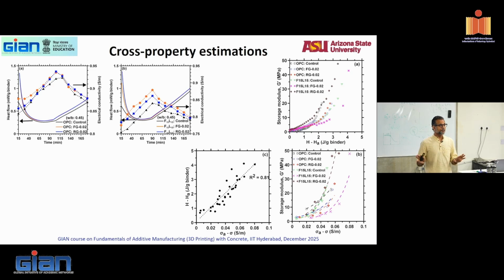So for durability, one is rapid chloride permeability. All of you use the RCP method for durability, right? Rapid chloride permeability is nothing but a conductivity method. It's a glorified conductivity method, which makes things actually worse and wrong, in fact, by putting in very high voltage and things like that, right? So RCP is an actual conductivity method, and in the US, we have gone away from the RCP method. Now we simply do, why waste 6 hours and 60 volts of potential? Don't bother. Just take a DC measurement, a 2 point or a 4 point DC measurement instantaneously, and move on with life. That's good enough.